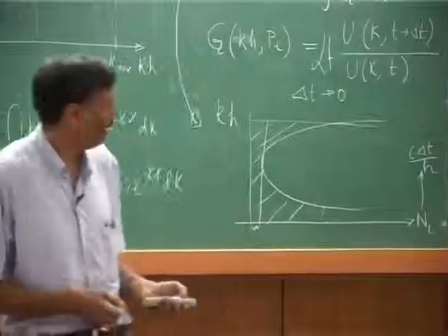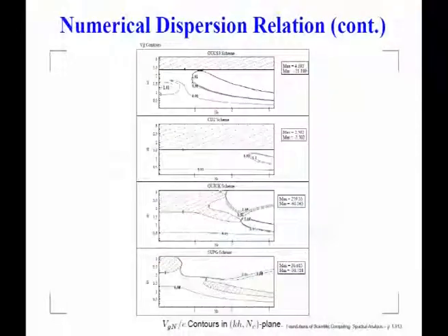For example, if I look at these 4 methods that we have shown here, this is a method which we have pioneered here. It is called compact schemes, which has some extremely good properties. This is the classical finite difference scheme. This is your finite volume scheme that is used in Fluent. You know, Fluent has its most accurate component, which runs on this algorithm called Quick. It has even worse parts, but this is the best Fluent gives, this Quick scheme. And this is what the finite element methods do.